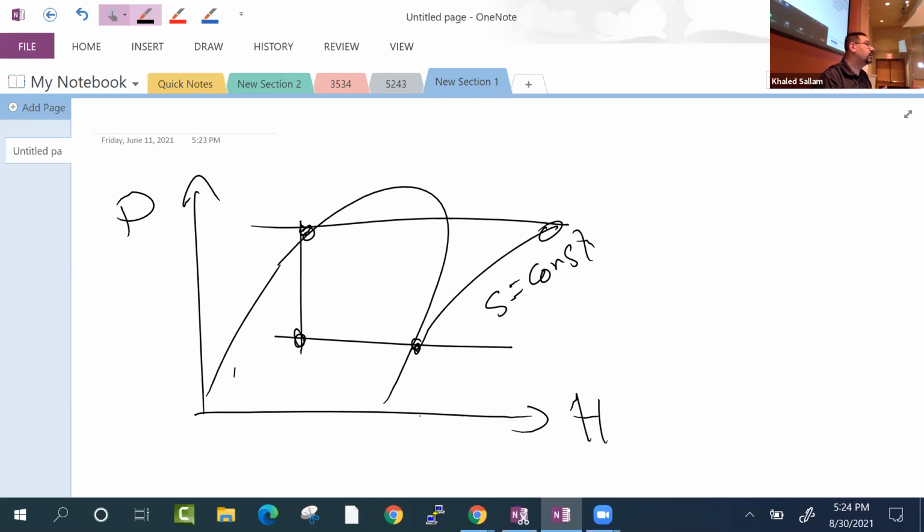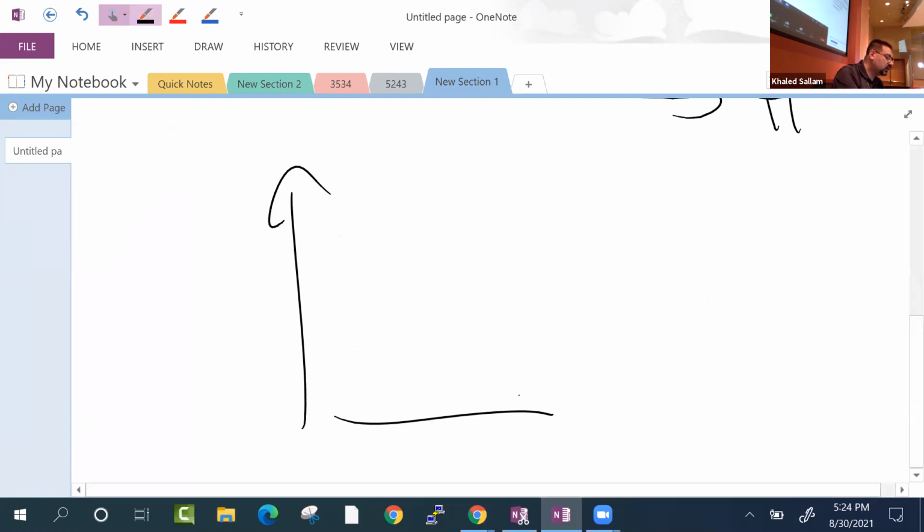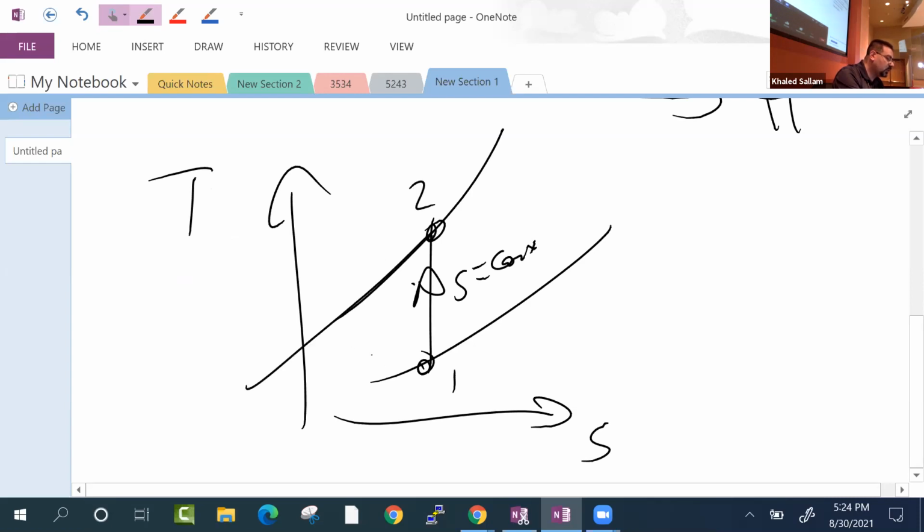Have you ever seen a multi-stage compressor? You do the first stage and then there's something you do before you go to the second stage. What do you do? You cool. You intercool, right? So an intercooler reduces the temperature and tries to achieve that dream. What dream? Rather than going, this is on the TS diagram, here is constant, right? And that's the isentropic compression. Surprisingly, the best work is not isentropic, but actually isothermal.